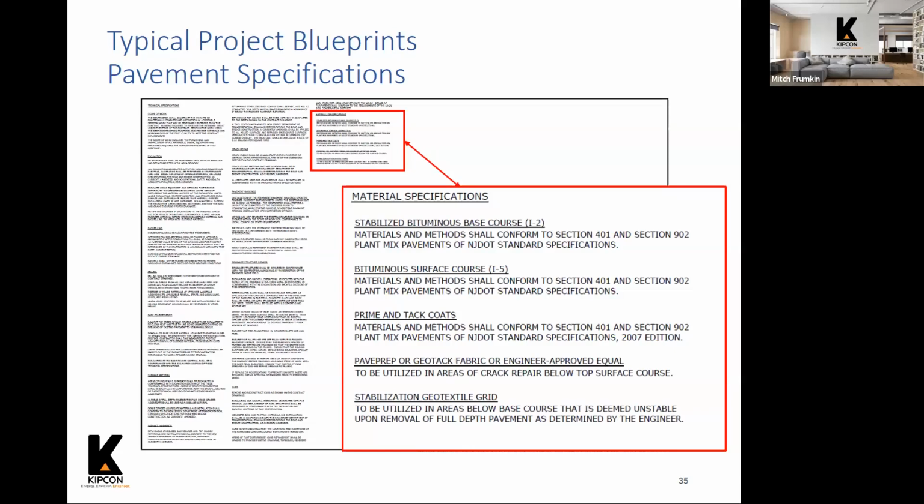for those are. Also, it's a little small on this page, but also there are instructions that refer to what to do when you are excavating or backfilling. You don't just throw some dirt in the hole and hope for the best. If you are backfilling, there's certain a standard for what type of material can be used, and how it needs to be compacted when you're backfilling, so that when the project is done, you don't end up with soil consolidation and sinking along the areas that you repaired.